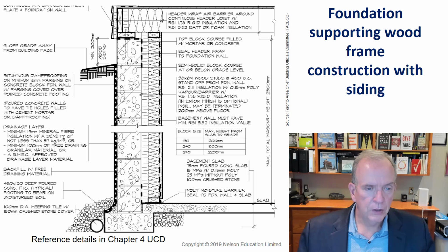We've got damp proofing on the wall. We'll talk about that. We've got a drainage layer that's on the outside. We'll show you some images of that later on. This is a symbol for styrofoam. So they put styrofoam on the inside wall, and then they built it in with a wood stud wall, and they've insulated that. Then they have an air vapor barrier by the looks of it there, and they have drywall here. And so you can sort of see component by component. You can also see there's an anchor bolt, that little angle here with the dashed line. The dashed line represents something that is hidden,